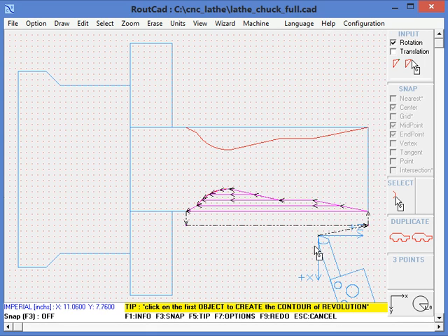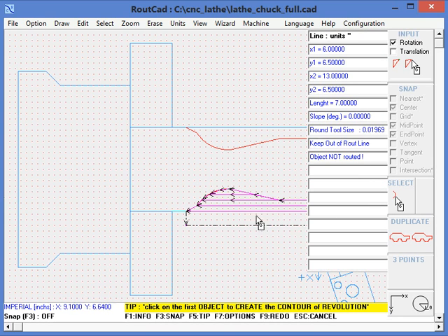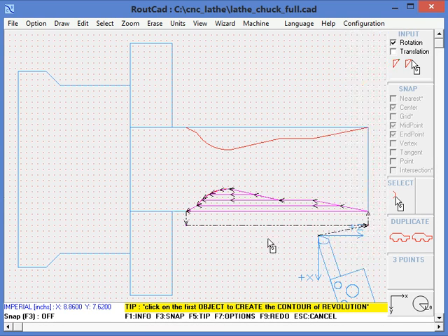It will basically move to another location half an inch away from the material, and it will actually machine through, and then keep on doing that until it finishes the complete profile. But there are no finish passes because we didn't specify finish passes.